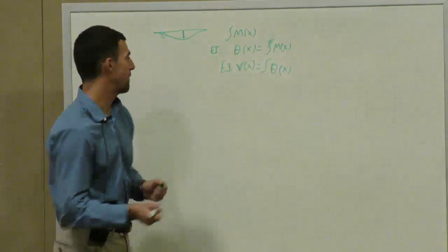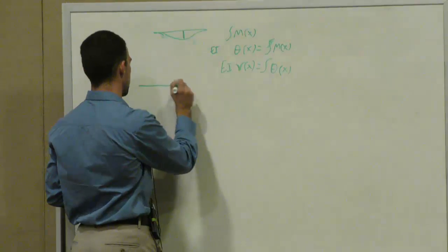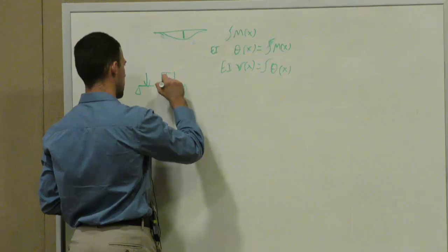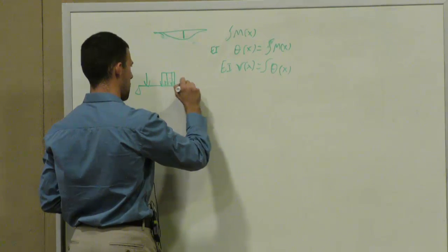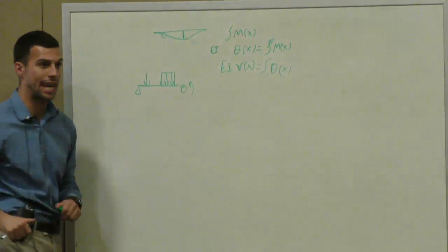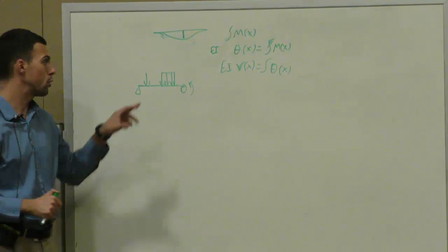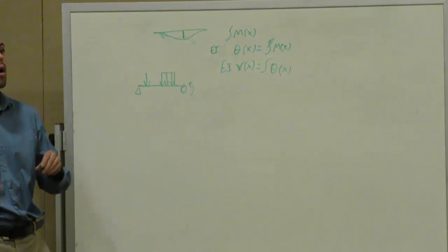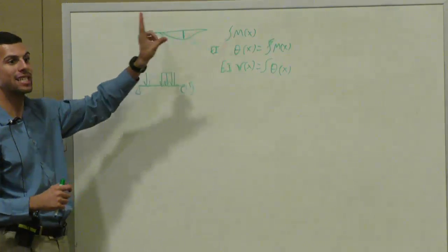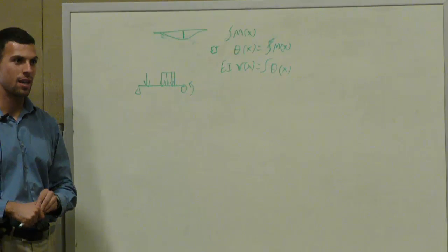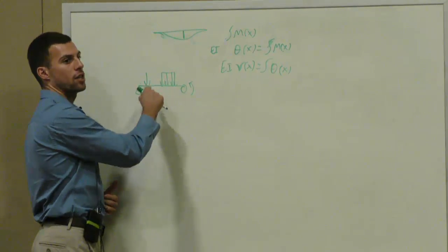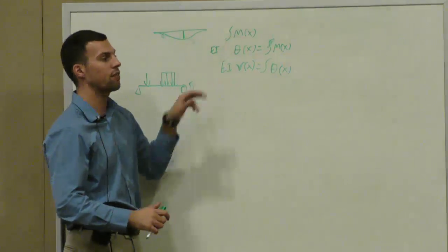Yes, right? If you have a beam, let's just do a very simple beam, subject to loads like this, is the moment equation here, here, and here the same? No, right? You can't describe this as a single moment function. In other words, you have to do this for every single one of those moment functions. And if you're asked to find the deflection of a point here, you have to know specifically its deflection equation.